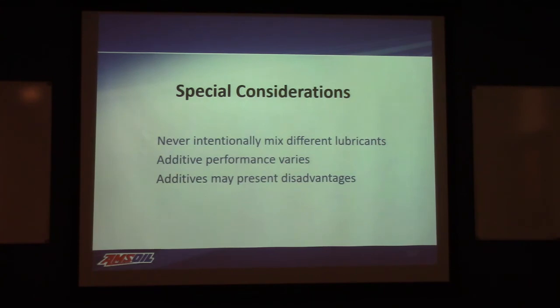Couple of things. Never intentionally mix different lubricants because the additive chemistry may be different. Okay, is this going to cause the tires to fall off your car? Is it going to cause you to lose the FM radio reception? You know, no, it's not. But long term, yeah, it can be an issue. We get into some specialty industrial applications. Mixing two can cause very, very rapid problems and very significant issues. So we don't want you to intentionally mix.